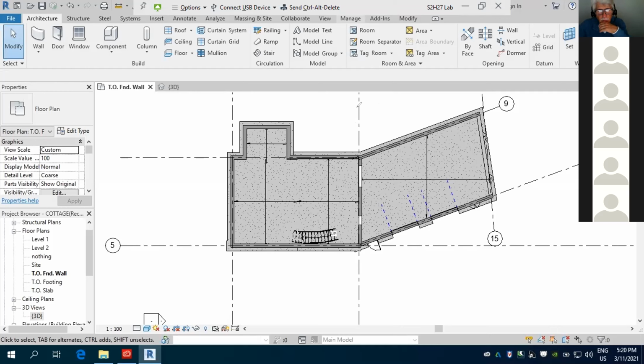Okay, so basically, if I remember from last week, we talked about the beam being right here. Am I correct? In plan view? Yeah. Okay. The thing that we didn't know is, are there any loads from the roof? In other words, when we're looking at a cross section, here's our floor. Here's our beam that's supporting the floor. Here's the exterior walls. Are there any partitions sitting on this floor, in this direction, right above the beam? No, there's nothing load bearing.